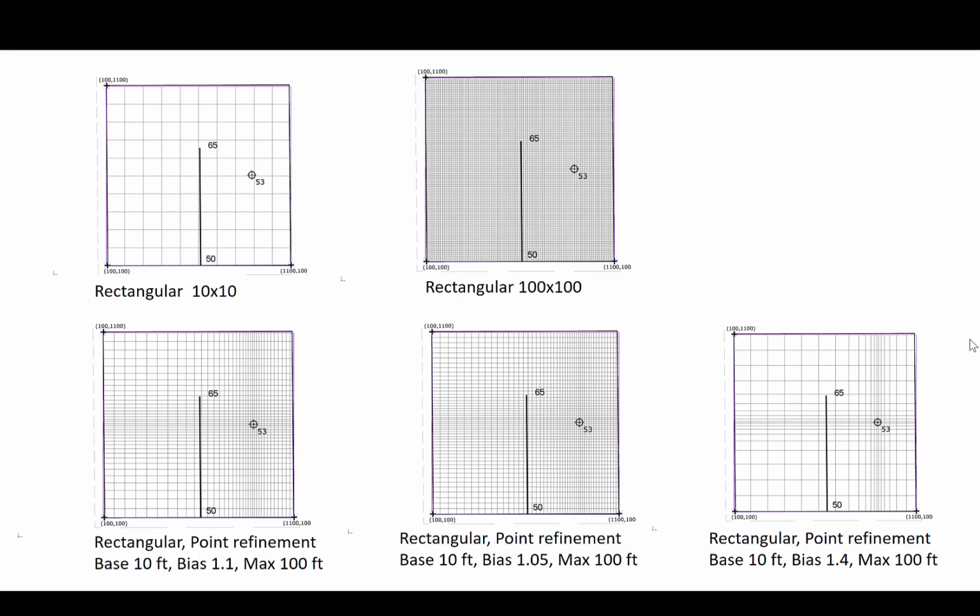This video will show how to set up 3D grids in GMS. We'll see a simple coarse rectangular grid, a fine rectangular grid, and then rectangular grids that are refined around well points using different bias factors.